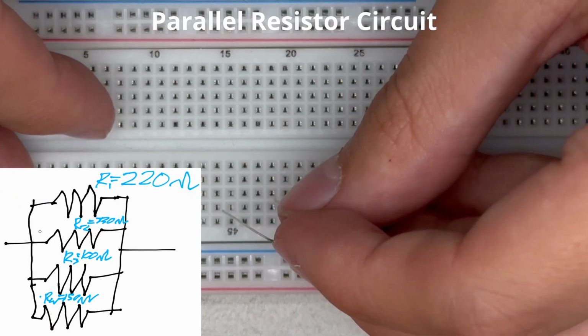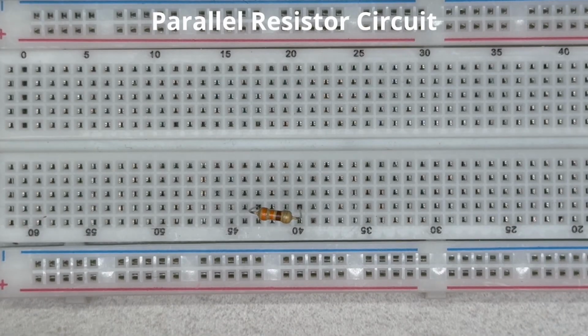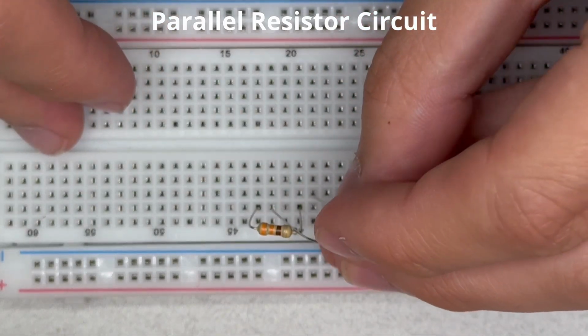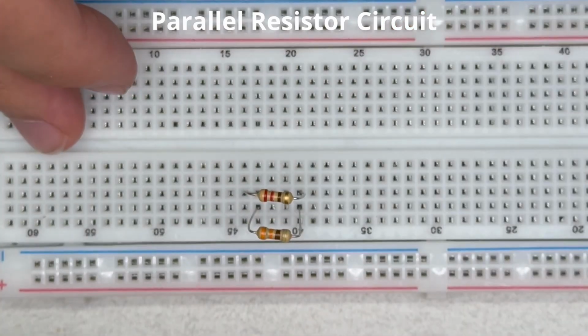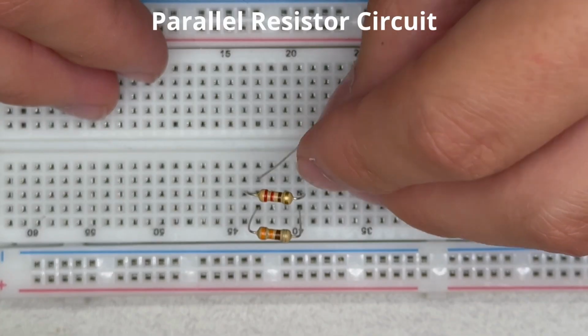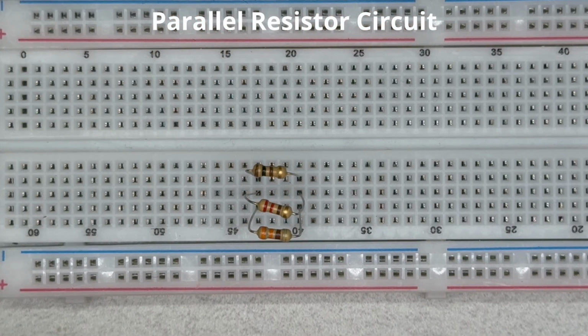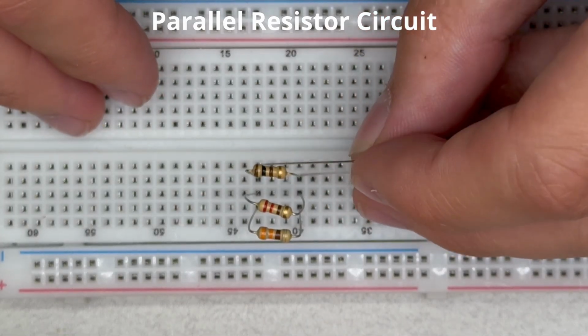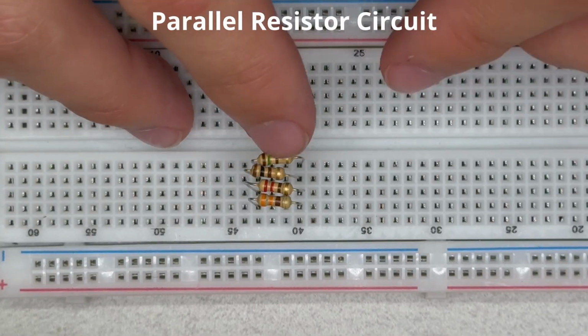Now we're moving on to the parallel resistor circuit. This setup is a little bit different, as in the breadboard each line on the horizontal or the vertical axis is all connected, so we're just going to connect them in a line basically. The main concept of this one is that the voltage drop is about equal on each side, so it goes from whatever 5 volt input to 0 output on the other side. But the difference is that the current will split among these resistors, with the majority of it going to whatever the lowest resistance resistor is.